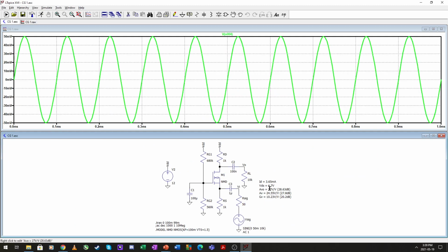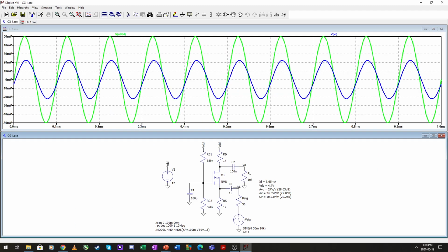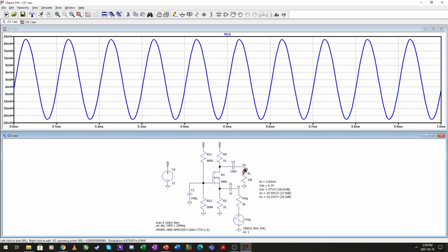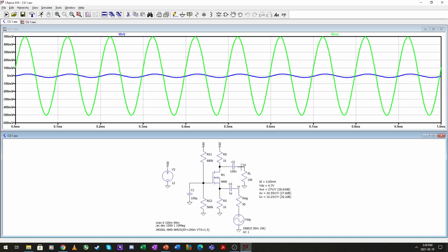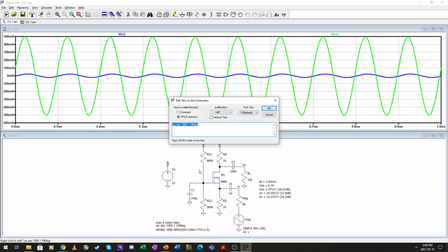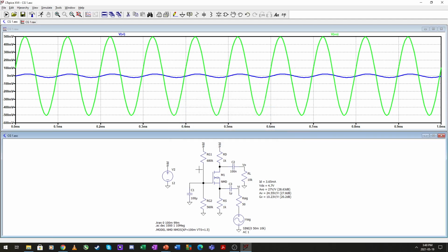So inserting 50 millivolts, that gets dropped down very far because of the mismatch we have on the input. So that becomes roughly 20 millivolts going in. And there is our output. So about 500 divided by 20 is, yeah, that's close to 25. And that's our common gate. Let's do an AC simulation here.